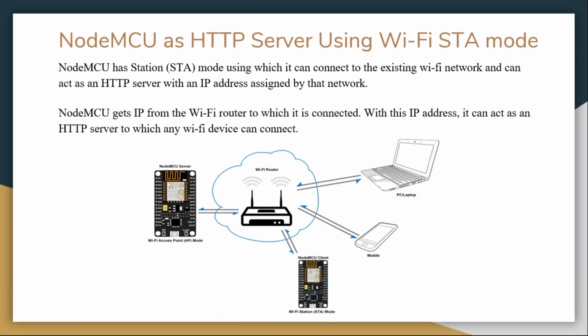When we are using the STA mode, the Node MCU will also act as a server while we are connecting our Node MCU to the specific router which has Wi-Fi functionality. Then the Wi-Fi router provides a specific IP to the Node MCU, and the Node MCU creates a node. We can directly connect to our node or to the router. We can control the devices through the router or directly through the Node MCU.